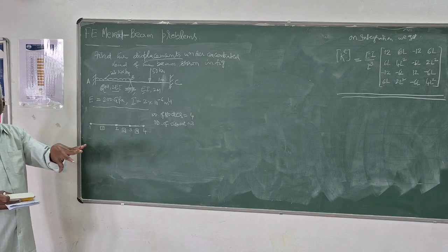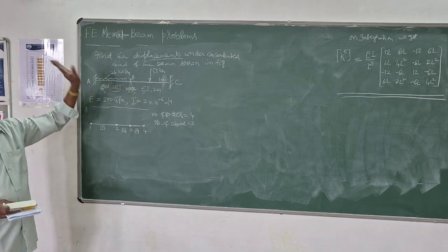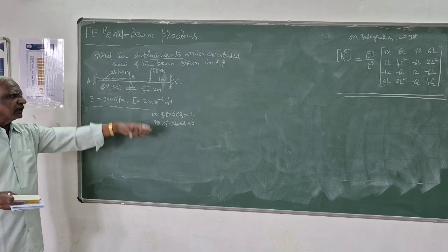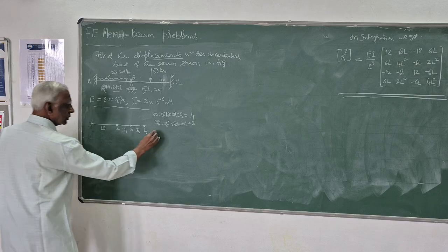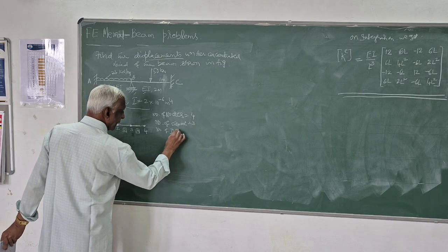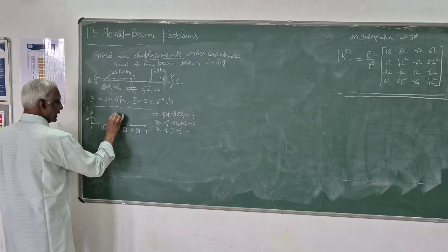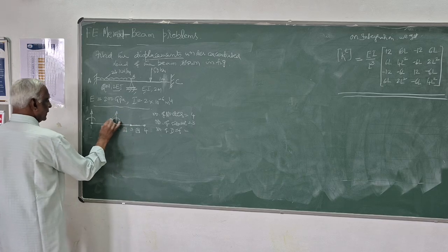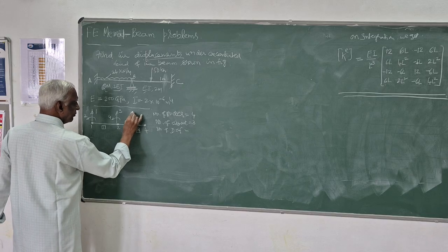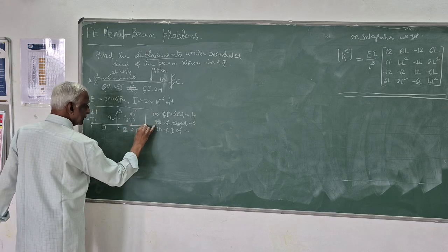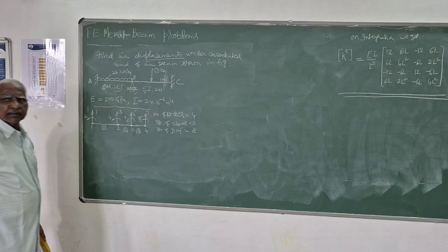In the isoparametric concept itself, we have 2 varieties. So the number of nodes will be more, and that node will be taken care of at the time of calculations of the degrees of freedom. So here, nodes and total number of degrees of freedom: at each node you have 2 degrees of freedom. Here 1, 2, 3, 4, here 5, 6, then 7, 8. Number of degrees of freedom is 8.